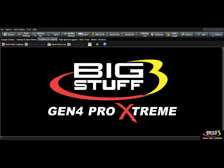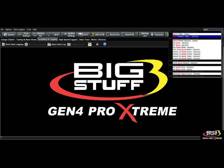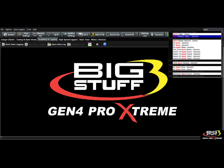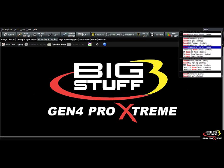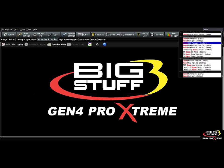This doesn't have to be fuel. This can be spark, so now I've got everything listed here under spark. Obviously there's a ton of stuff having to do with spark advance. Or maybe I just want to look up boost, and I get all this different stuff related to boost. So that search bar can come in really handy depending on what you're looking for, and if you're more comfortable finding stuff that way and getting around the software.